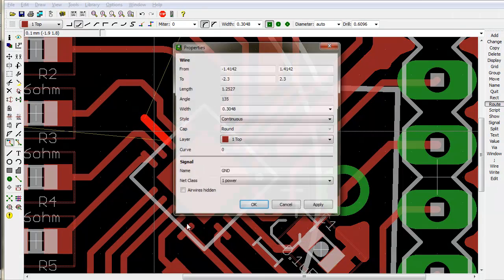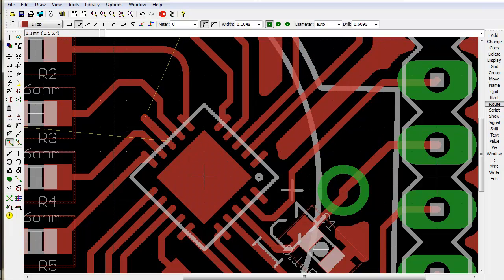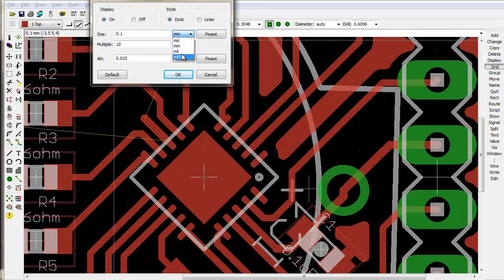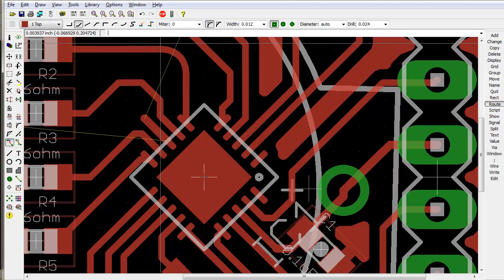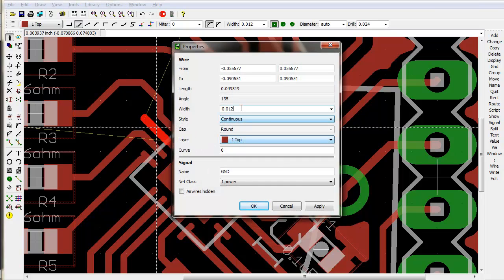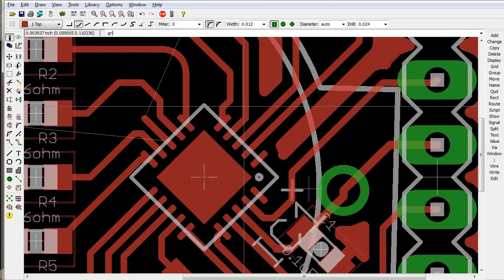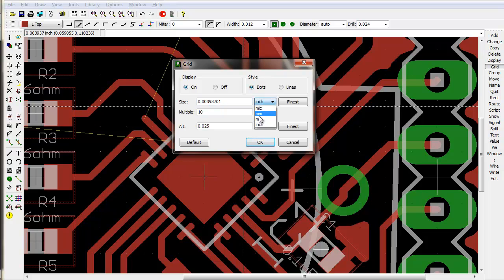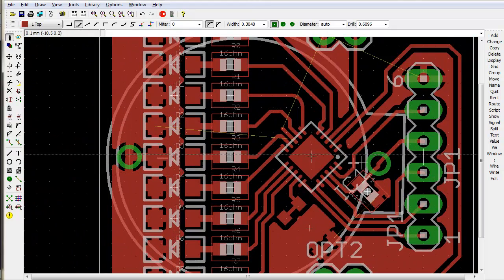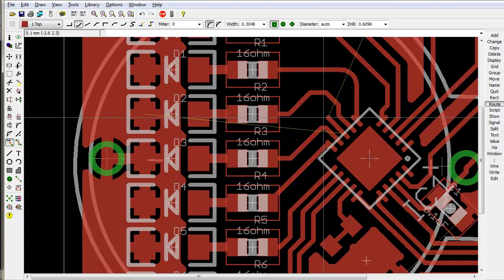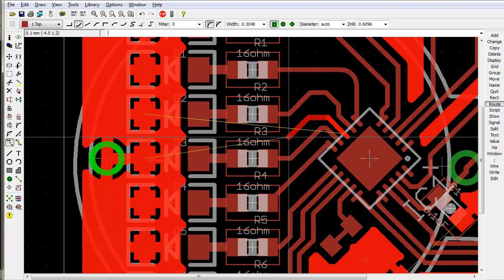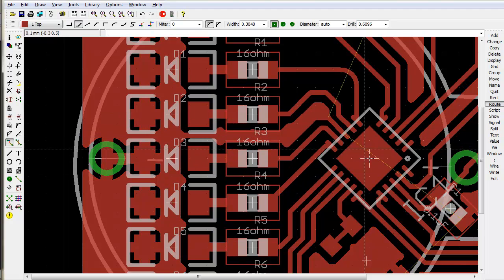We're going to change the width on it because it's a number that I can't remember, so we'll have to switch back again. See, this is called being stupid. 12, good. And doing this part. Okay, routes. Could obviously do all that later instead of keep doing it. And you can see it following it around. That's called follow-me routing. I'm going to squeeze up here, and now it's added. And there it goes. It filled it in for us.